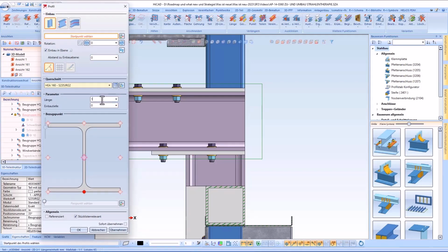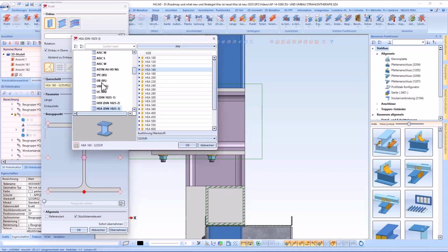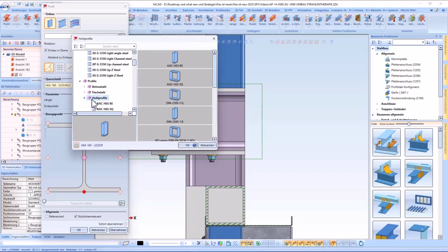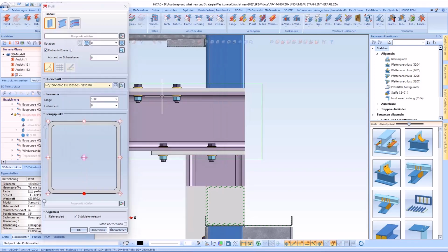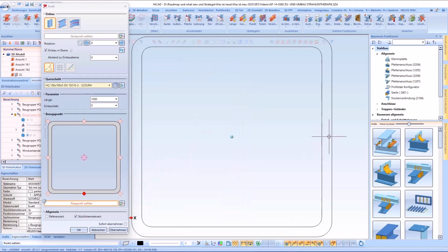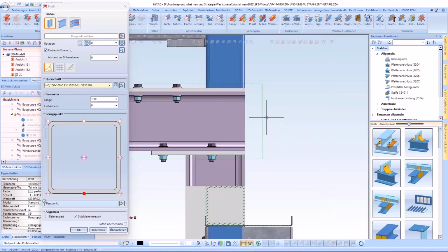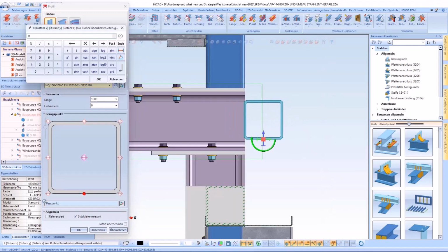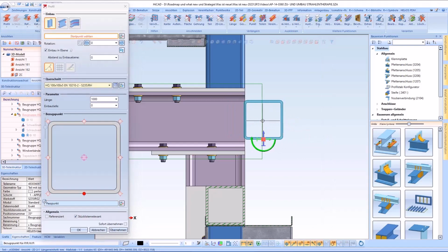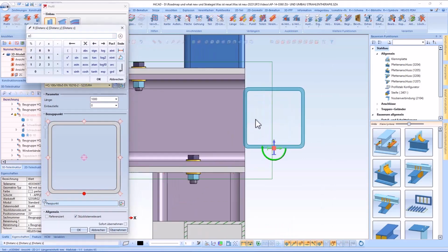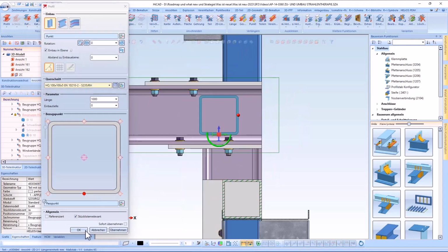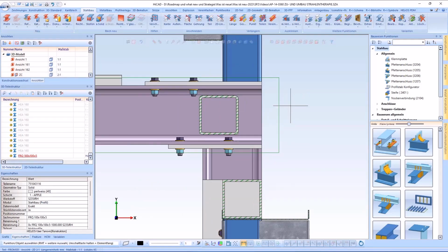After selecting the beam type, select the fitting point option in the dialog. Subsequently, any point on the beam cross-section can be selected via the graphic preview, which is then used during insertion via the relative coordinates. For a possible further beam exchange, the point must be selected again.